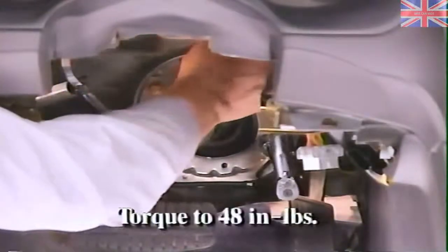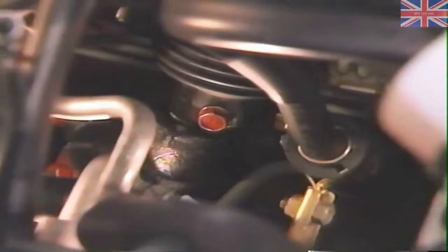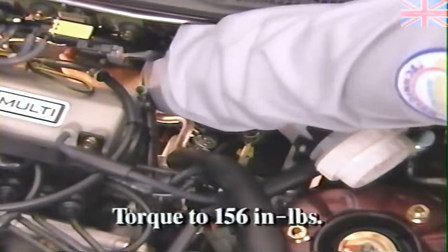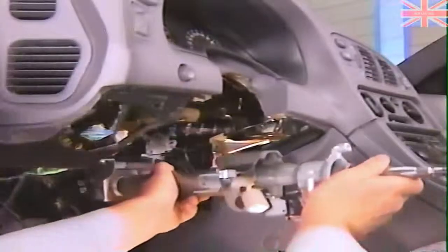Install and tighten the 4 retaining bolts to 48 inch-pounds. Then replace the pinch bolt that holds the shaft to the gearbox valve housing, tightening it to 156 inch-pounds. Install the new steering column and shaft assembly, lining up the splines of the intermediate shaft with the splines on the steering shaft.